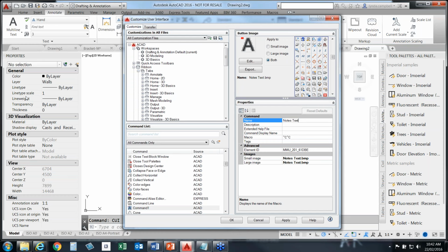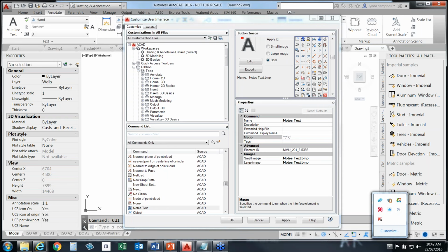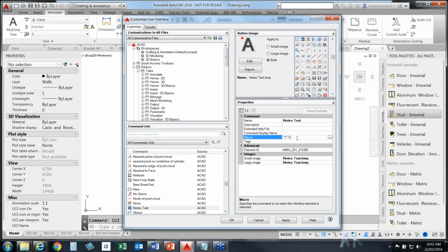Again, just to save time, I have created the macro. So cancel, cancel, layer command, S for style, it's going into the text layer. The semicolons separate the different commands, but keep it all within one command environment.